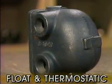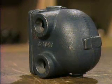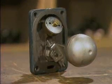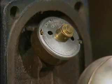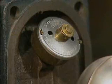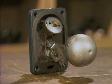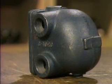This is a float and thermostatic, or F&T trap. It's generally classified as a mechanical trap because one of its major internal parts is a ball-type float mechanism for removing condensate. However, it also has a thermostatic bellows that reacts to changes in temperature and is used to remove air and non-condensable gases. So in this respect, the trap is thermostatic. More information about thermostatic traps is given in the part of this topic that's entitled Thermostatic Traps. For now, let's look at how a typical F&T trap works.